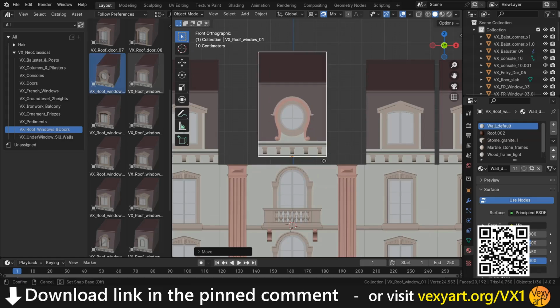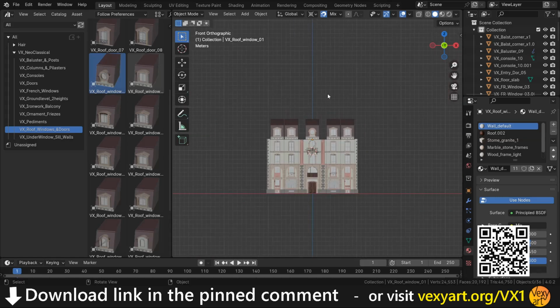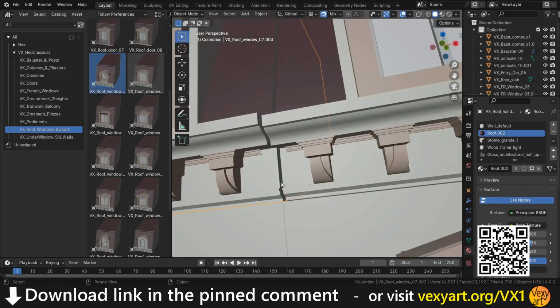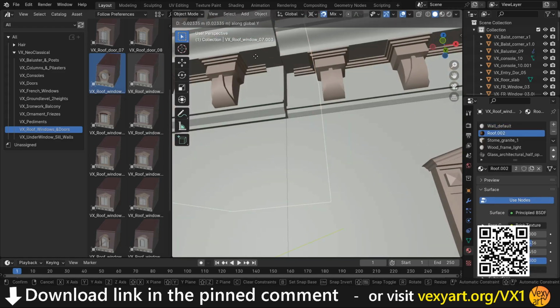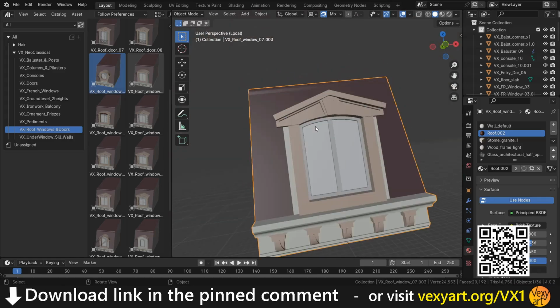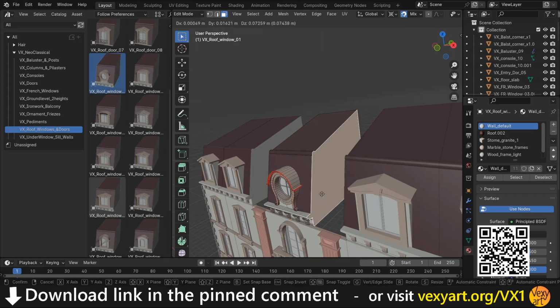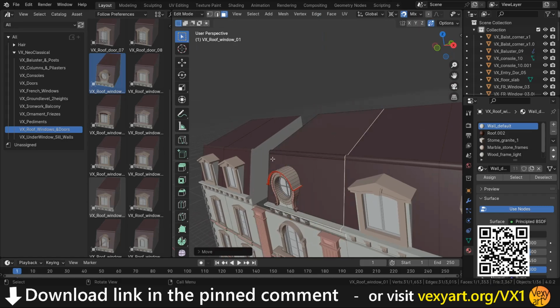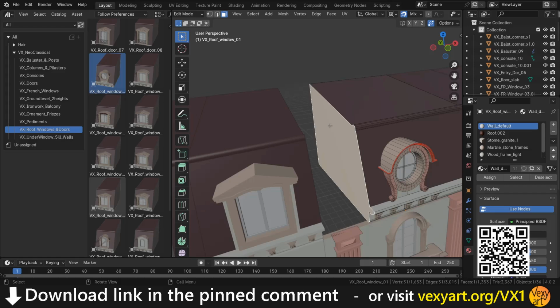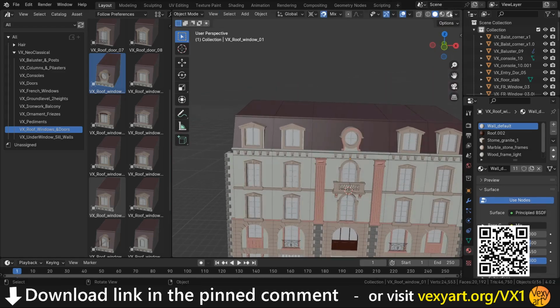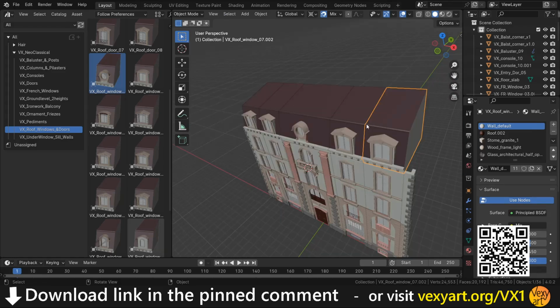Make sure to center all the windows and blocks with those below and above them, before extending the faces. In edit mode, make sure that the correct face attributes is checked under options, otherwise it might stretch the textures applied. Now is the time to edit the used elements to form a continuous and coherent facade. Select the window blocks that still have spaces between them, enter edit mode and extend or stretch the walls onto the adjacent elements. Join the roof segments into one object, merge the meshes and faces for the UV to span the whole length of the facade.